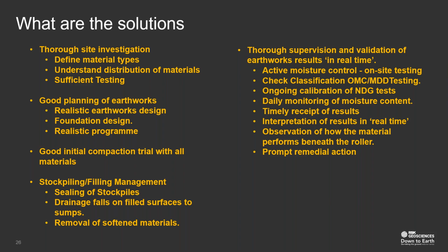The method specification in the specification for highway works is a good basis to start from. By modifying that and coming up with a definite method to work to, you're improving your chances of hitting your end product and performance targets at the end of the job. I mentioned the need to manage the site properly so that we keep our materials dry and we preserve the quality of the fill that we've placed.